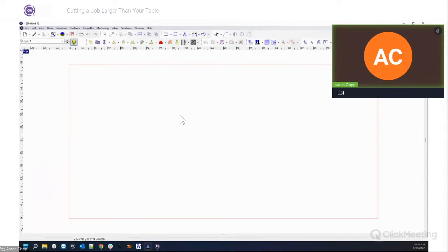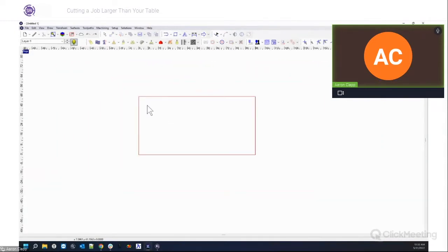Some of the old traditional methods were to set up dowels and create a design on your screen, and then shift it over using the move command, or change the origin of the plate so that the plate would move origin. All of that worked, but had inherent problems: you might run into errors, or easily make a mistake in positioning, and then your cut's ruined.